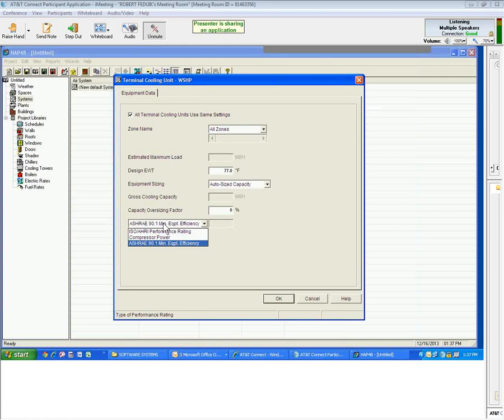You go ahead and run a quick operating cost that represents equipment that's within ASHRAE compliancy. Or you can put in something better than ASHRAE. Or you can put in the as-built compressor power if you're looking, let's say, at a submittal. We have various options to model the efficiency of the equipment. And when do you need the efficiency in a program like HAP? When you're going to do an op cost.